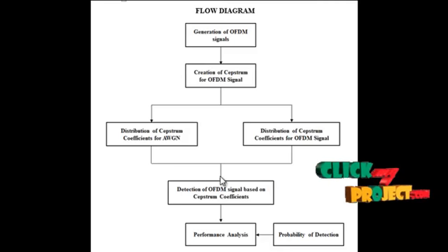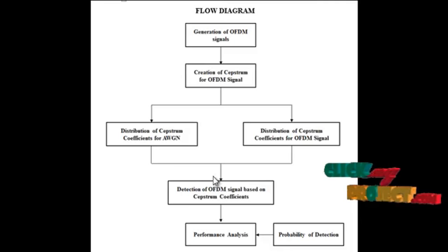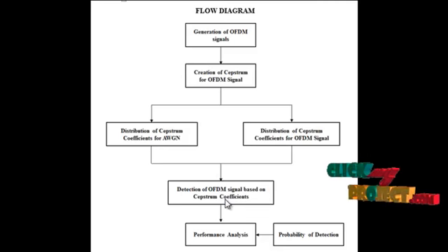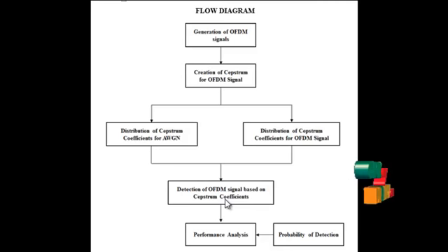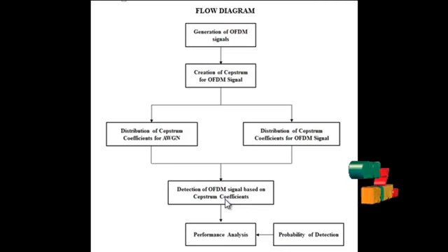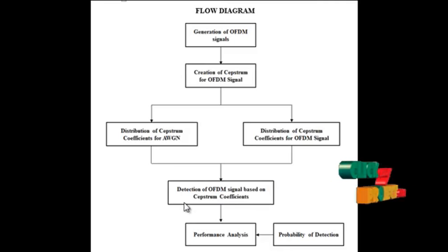In this section, we treat S of n and W of n as uncorrelated, and we derive the detection of the OFDM signal based on the above estimated Cepstral coefficient. With it, we can easily obtain the detection of the OFDM signal.